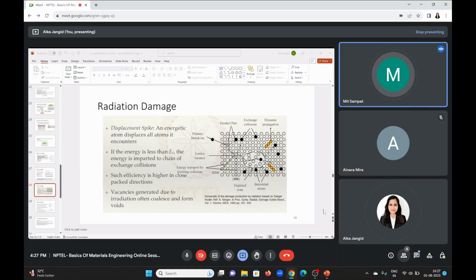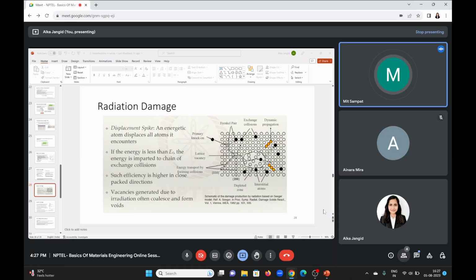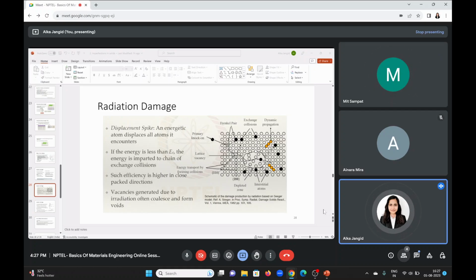Depending on the Schmid factor, your shear strength will change. You have read the Schmid factor, right? Schmid factor is how your slip system will be aligned along the tensile pulling direction that you are using. So depending on that, it will keep on changing.